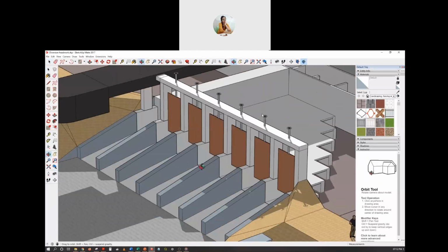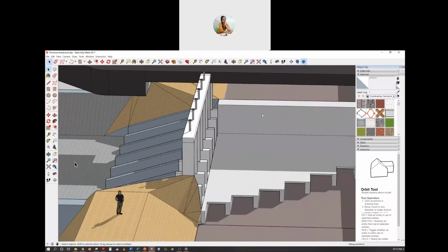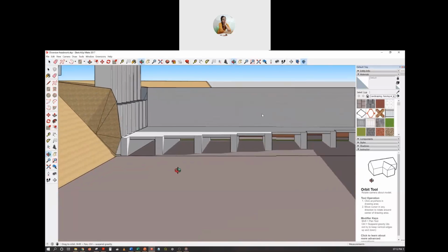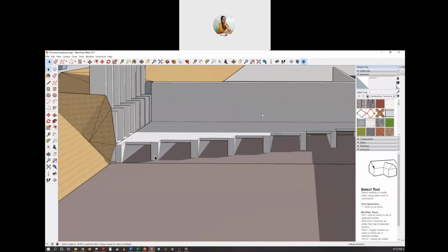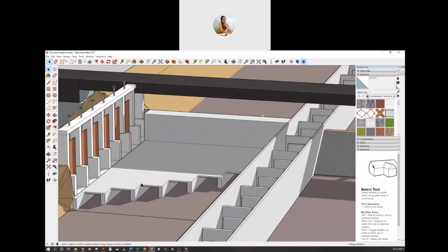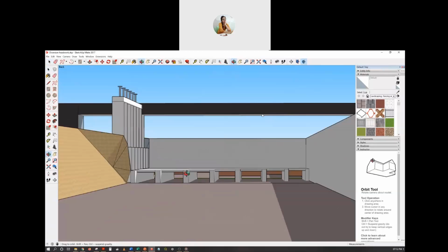Now, this part, these tunnels are called silt excluders. What they do is, when water flows to this location, the silt carried by the water will be mostly carried near the lower part of the flow. So that part enters this portion, these tunnels. If you see, those tunnels lead to the downstream.